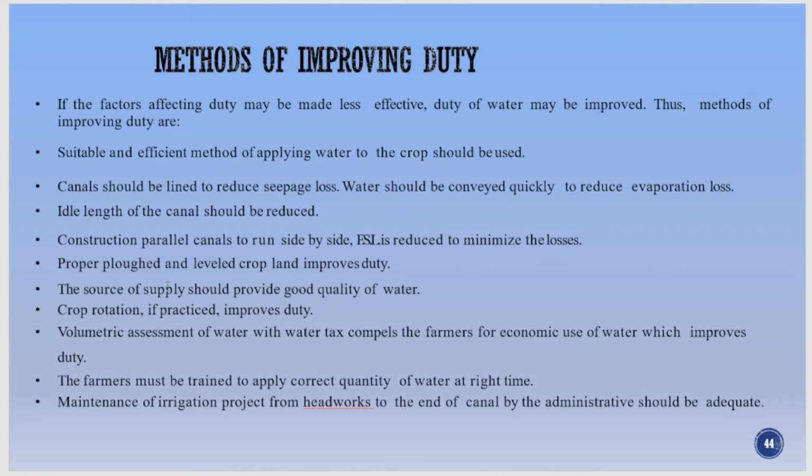There can be evaporation losses, and seepage losses within the body of the dam itself. Those are the losses that take place. When the water is supplied through canals, the water carried in the canal may also evaporate or seep out. So there are seepage losses while conveying the water and while storing it in the reservoir.